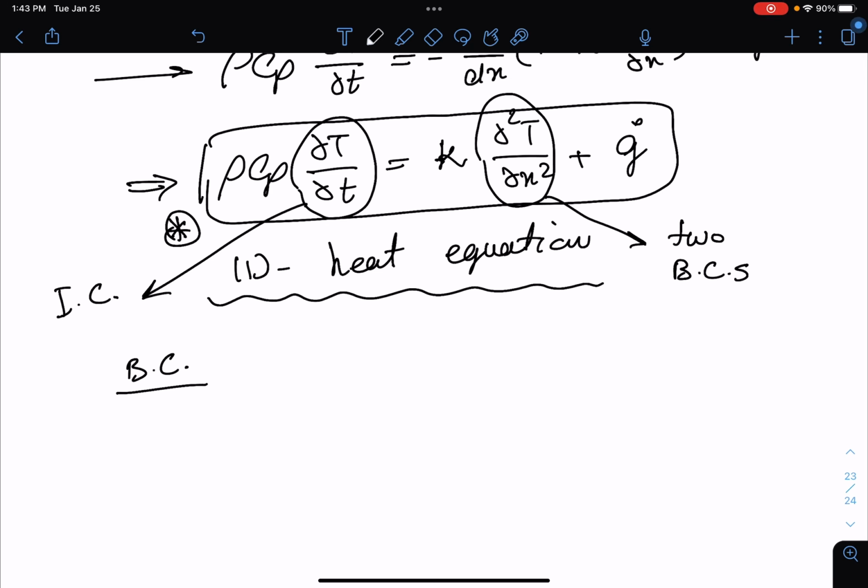What if this problem was a 2-dimensional steady state heat transfer problem? How many boundary conditions would we need then? 4. A steady state means that it is not time dependent. So the time dependence is gone here. And we will come back to that part later. The initial condition part is pretty easy to understand. We only give the temperature at any location x, at time 0.